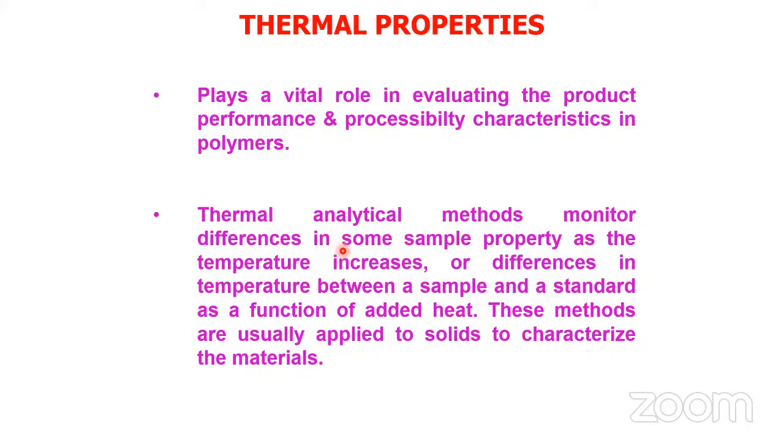Then the thermal analytical methods monitor differences in some sample properties, as we increase or decrease the temperature of the sample, or between a sample and a standard as a function of added heat. These methods are usually applied to solids to characterize the materials, to determine the thermal behavior, meaning the behavior of polymeric material in presence of heat or thermal